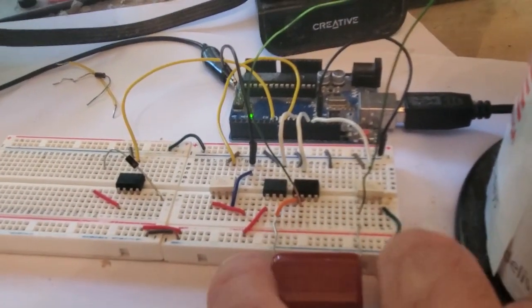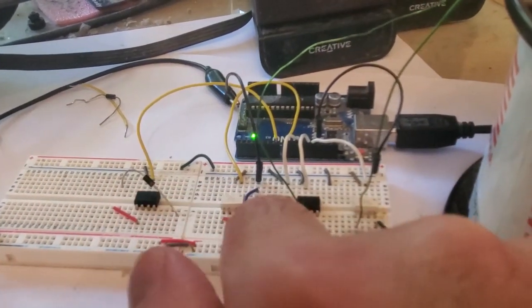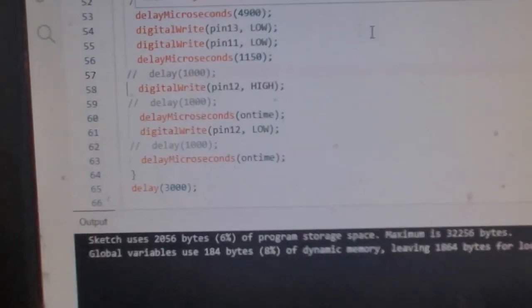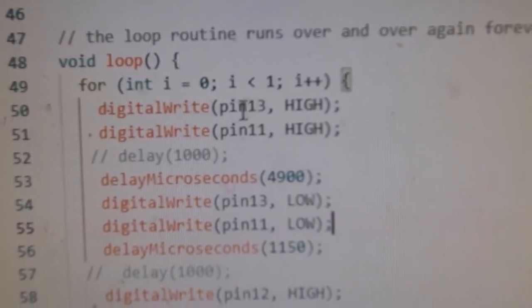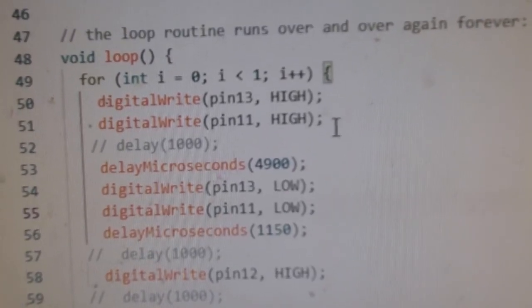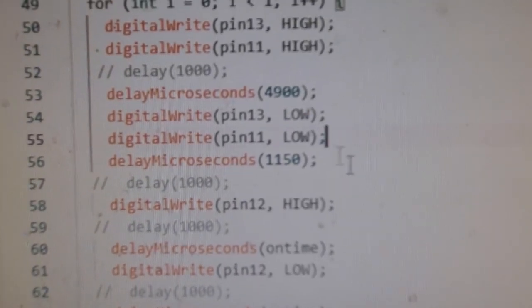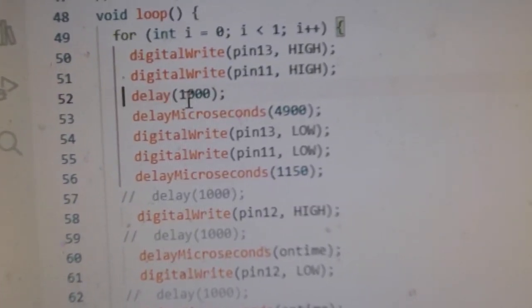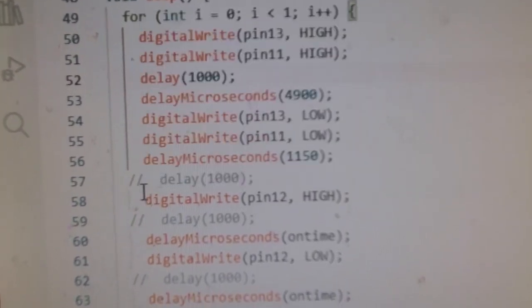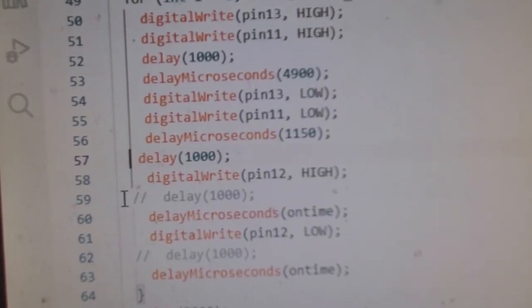So that's your circuit. You just charge up a cap and then discharge it. We're not going to be doing anything with these today because there won't be time. And then here's the code for it. We don't even need the for loop, but we'll just do it once. So we say pin 11 high, that charges the cap, then pin 11 low, then pin 12 high and pin 12 low. I have these delays for a second. Let's go ahead and put those in just to be able to see that everything's working correctly. That'll just show us that it's working.